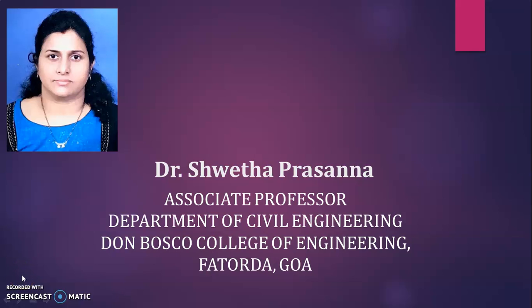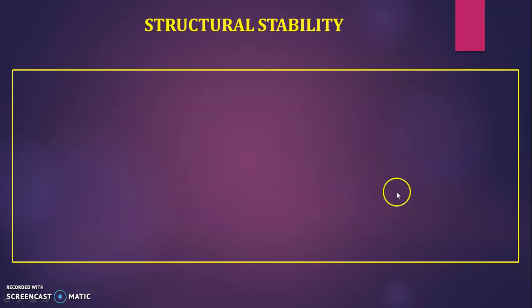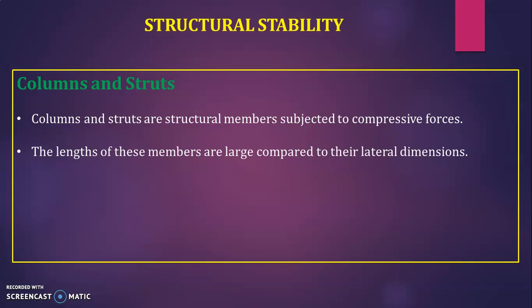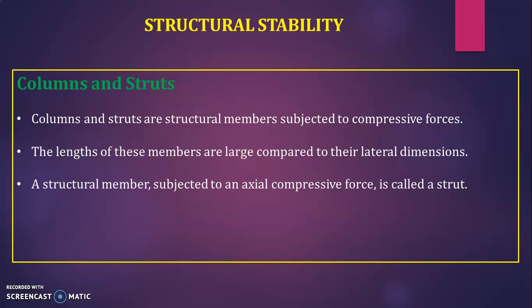Hello my dear students, let us start with the next chapter, structural stability. Here we are mainly dealing with the columns and struts. Columns and struts are structural members subjected to compressive forces. And here the lengths of these members are large compared to their lateral dimensions.